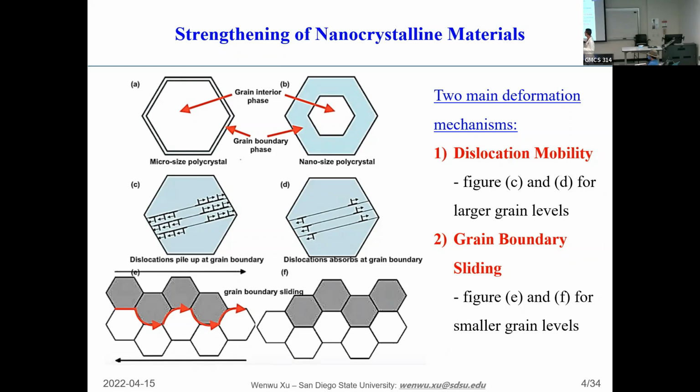We call this a grain, and it is surrounded by the grain boundary in the microstructure. Those dislocations can easily generate in the grain, and then they move and accumulate along the grain boundary. And in this, the dislocation activity as well as the deformation is taking place.